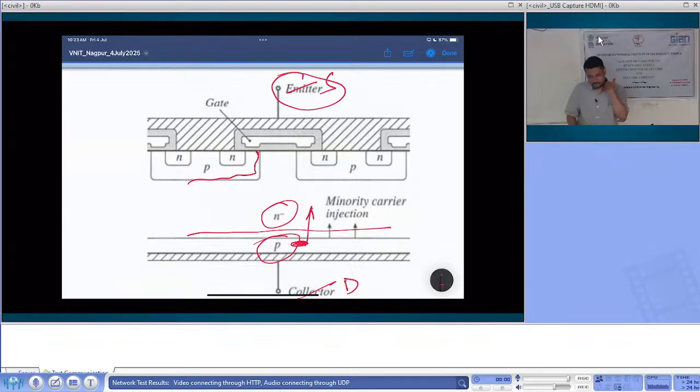So the IGBT is not a BJT? The IGBT is a BJT. It's an extended version, insulated gate bipolar. That's what I thought. Correct. It is a BJT, but it is insulated gate. Correct. The difference is that the P layer is an addition here, as compared to the MOSFET. Yes. And it helps if you want to build a high voltage device, because it allows minority carrier injection. It's like a restriction to the P layer, not any restriction to flow. So now that is the point.